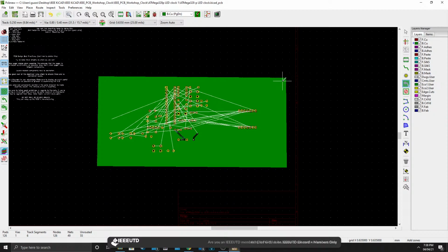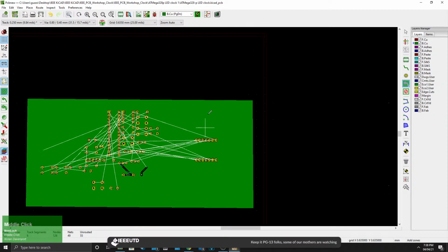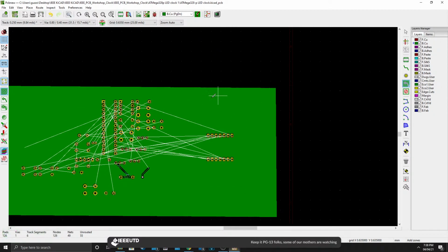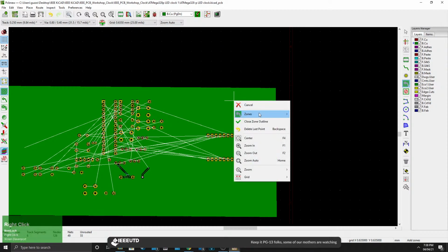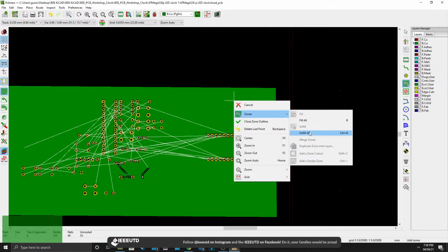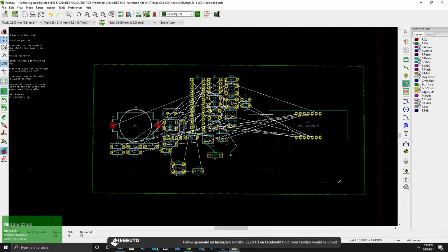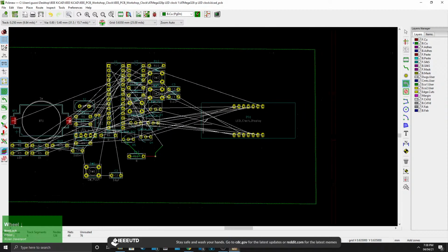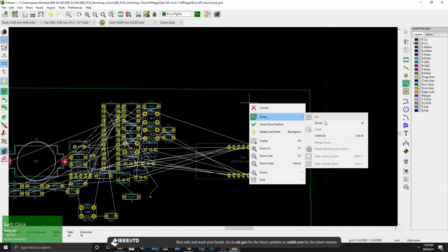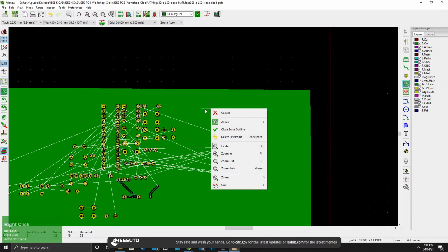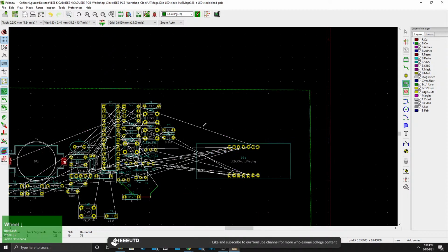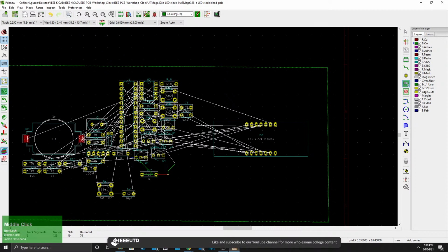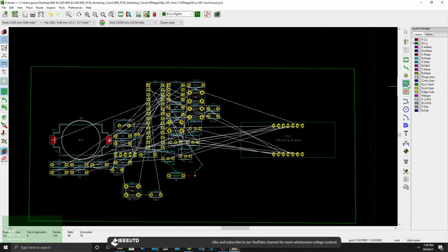And while you're working on the PCB and making changes, instead of deleting the whole filled zone, if you add a new ground, you can right click and actually unfill all, and it kind of has an outline, but it removes the connection. So if you add a new component that has a ground, you unfill it, and then right click it, and then you can actually fill it again. And also it actually helps with working on it. So if you unfill the zones, now it's easier to work with. So that's a ground layer, and now I actually kind of want a layer for the VCC.